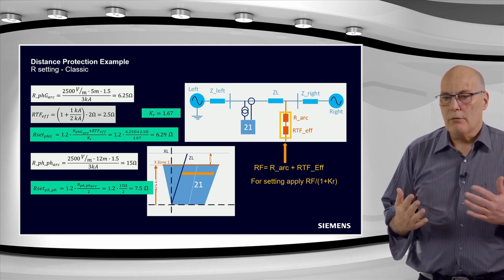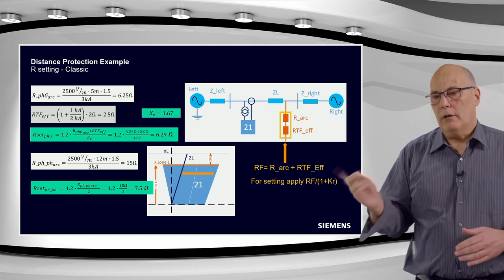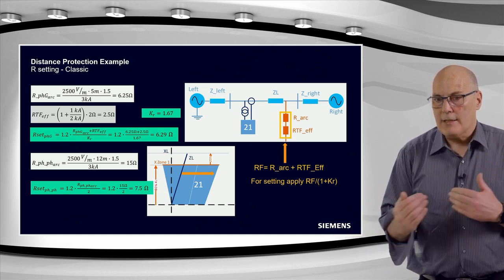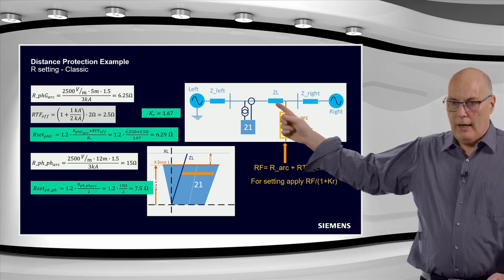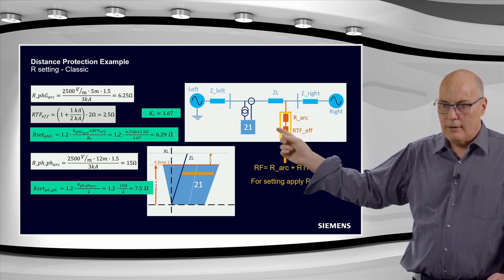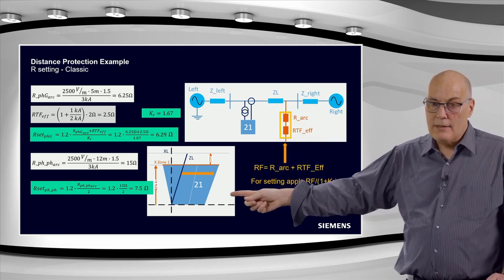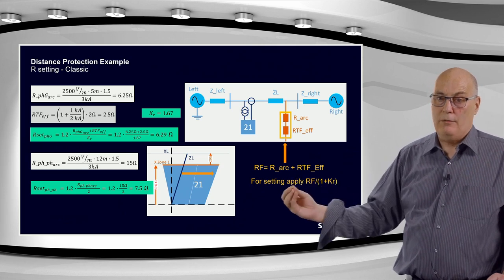It is because the equation that we're using to calculate the ground resistance, as shown early on with those factors, extracts the positive sequence impedance. Remember, we have here the loop current will be the ZL out and the ZE return, but measured and applied in this curve here is only the positive sequence impedance.